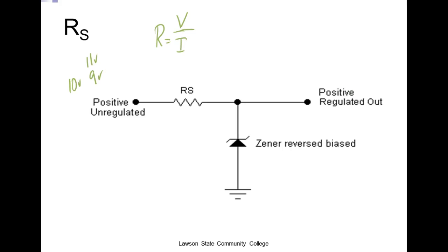Okay, so what size Zener? What's our Zener voltage? Got to have it. It's got to be less than 9. We've got to have a Zener that's below where our unregulated voltage is changing, right? So what do y'all want to do? Now let's do a 6-volt Zener.